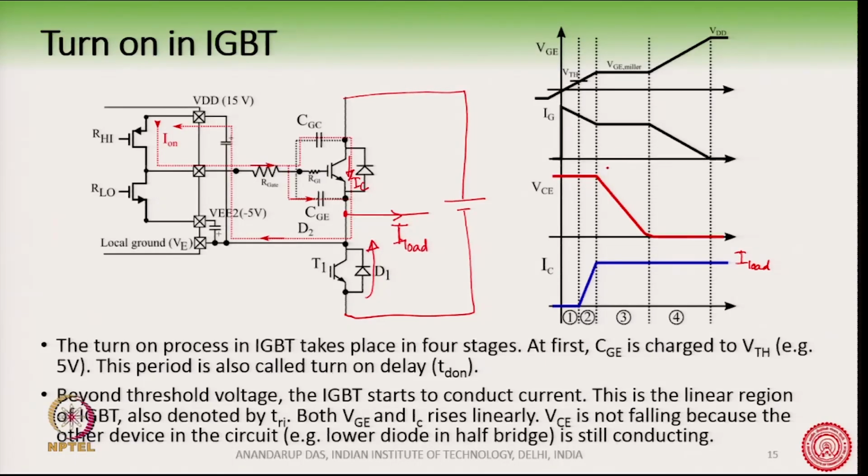Okay. So, this is the DC bus voltage, so this voltage will be VDC bus here. The voltage across the IGBT is equal to the DC bus, whereas the current is rising up here. This is a stage where there is a loss in the IGBT.